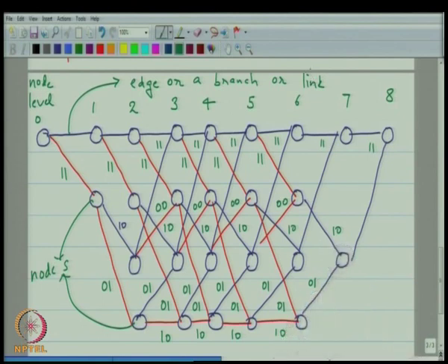And now, another thing to keep in mind is that the way we have colored the edges in this graph is that whenever the input is a 0, we have an indigo colored line, and whenever the input is a 1, it is red. That means that if I feed the encoder a particular information sequence, for instance the all 0 sequence, then I will be tracing out this particular path in the trellis.